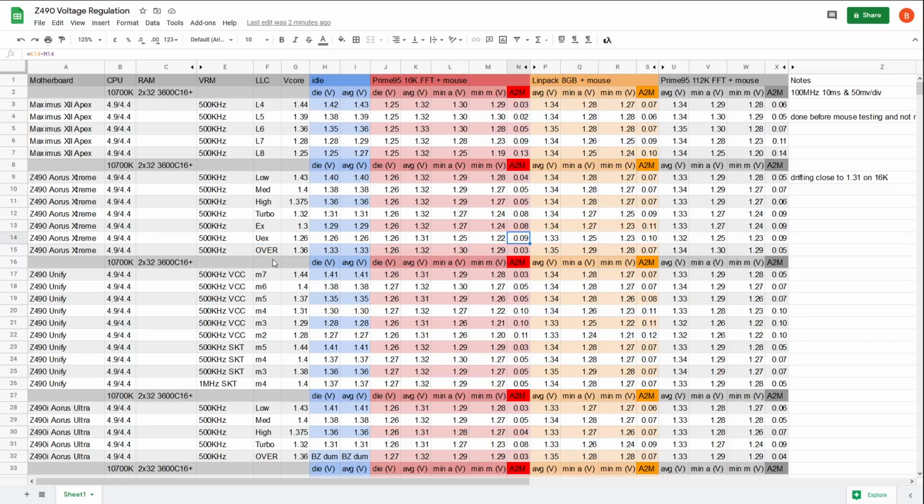What override mode does is it gives you a non-stupid dynamic voltage mode, but it still has all of the V droop, so you don't get the voltage regulation issues. If you actually watch your VID readings while running override mode, it does very strange things. But yeah, in my testing, override mode has just been absolutely amazing. It does so well, because you can set an even lower set voltage than with high. And this is especially an advantage if you're on a 10900K, because as far as I know, override mode is set to match against socket sense.